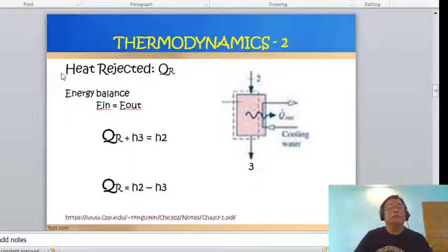So the assumption, of course, is that all are constant pressure. So if we isolate one system, of course, in the entire cycle, say for example the boiler or the condenser, isolated from the system, we treat that as constant pressure, class. That's why we are going to assume that energy entering is equal to energy leaving.